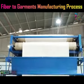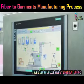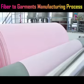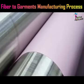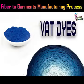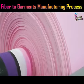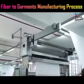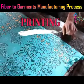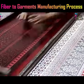Dyeing is the main process where white or gray fabric becomes decorated with different colors. Dyeing of textile substrate is performed using any of the dyestuffs including reactive, direct, sulfur, vat, pigment, acid, and disperse, depending upon the dye-fiber system compatibility. Printing is known as localized dyeing. Printing gives a spatial appearance on colored or white fabrics.